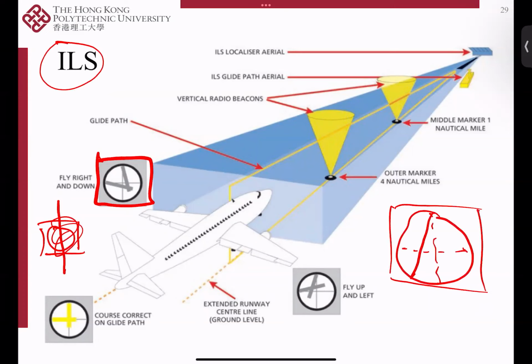If it is not in the center, it means you are already deviated. What you do is follow the line, going with the line's direction. For example, if the line is on your left-hand side, you make your aircraft go to the left-hand side. So let's look at this example. You have this line, so what you do is follow the line. The vertical line is related to the localizer, and you need to trim your aircraft to the correct direction, and you need to move to the right.